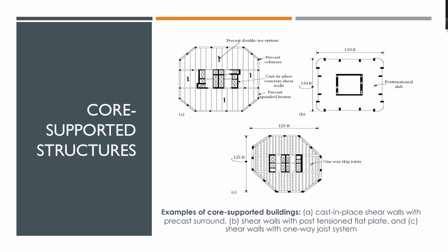So it's quite now possible to use a core with post-tension slab. Look at this one, what I'm talking about. There is no column, there is nothing there. Okay, so this is very interesting because it completely eliminates any beams from the floor, just outer columns and core, and all the lateral load carried by the core. Wall has nothing to do with it. So you don't need the framing action. So this is quite useful, and these are all from real buildings.